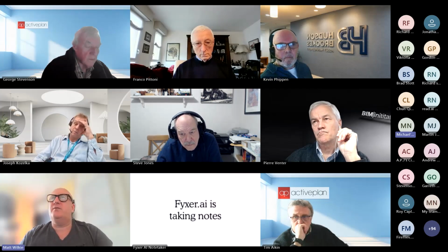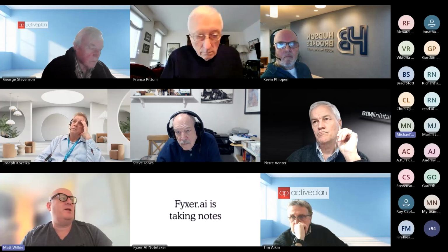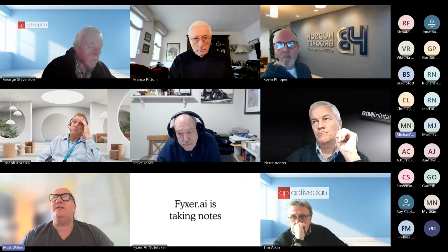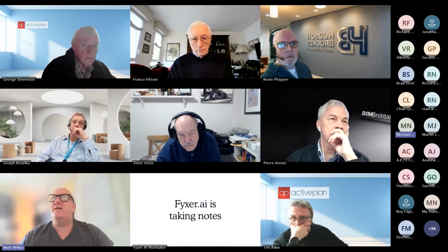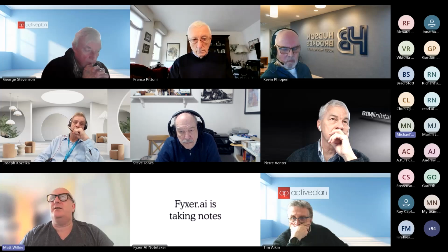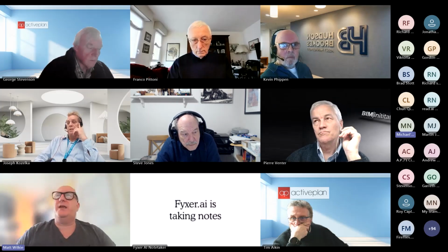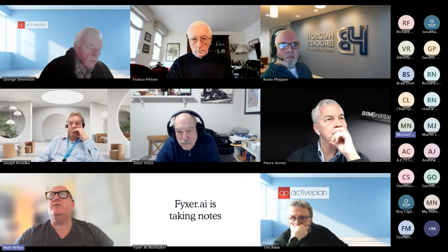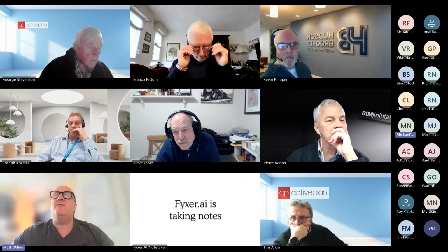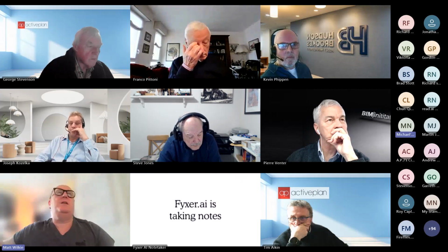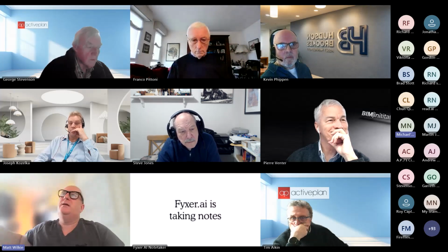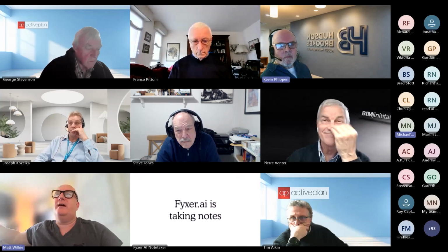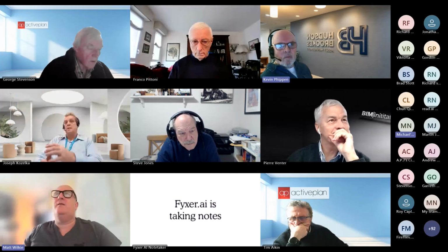Yeah, 100%. I'd also say this is partly why it's important that people update the RDSs. And when they do the ventilation changes, I think it falls under Part F of the building regulations, isn't it? I'm sure it's Part F. So you're supposed to take air changes into account when you do those changes as well. So you're 100% right. If a wall's moved, the ventilation may be in a completely wrong place now. I've been in schools where all the supplies and extracts are together, and I look at it and think, well, I know what's happened there.